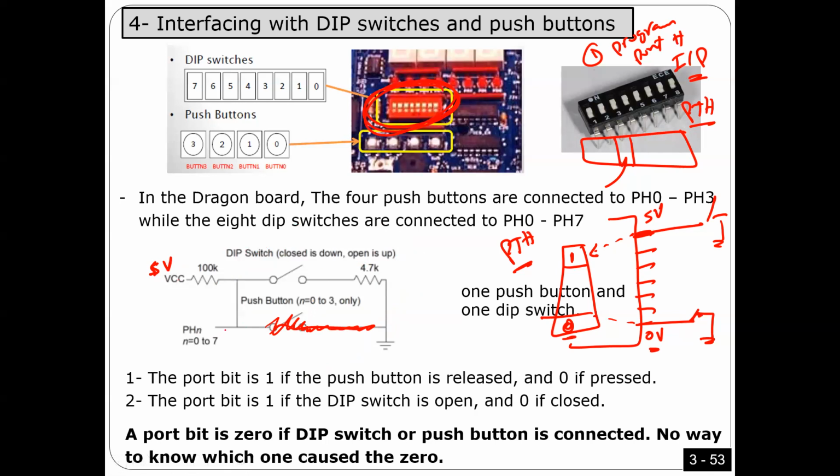So let's see how it works. And this one is connected to the pin. This is a microcontroller connected to the pin. Look here, guys. If the switch is open, very, very little current is going to come here because this is the input of a transistor. Very little current. So that means if this is 5 volt, there is almost no voltage drop here, so this one also would be 5 volt. You got what I'm saying?